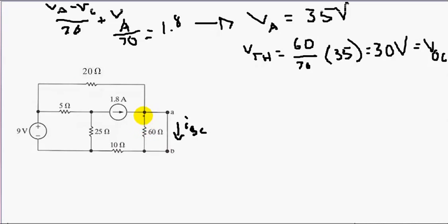Notice that when we short this, the resistance has the same voltage as this wire. Because they're in parallel, when you have a resistance in parallel with a short wire, you can cross this out because it will have no current, because of Ohm's law, V equals IR. The voltage here is the same voltage as across A and B, which is 0.